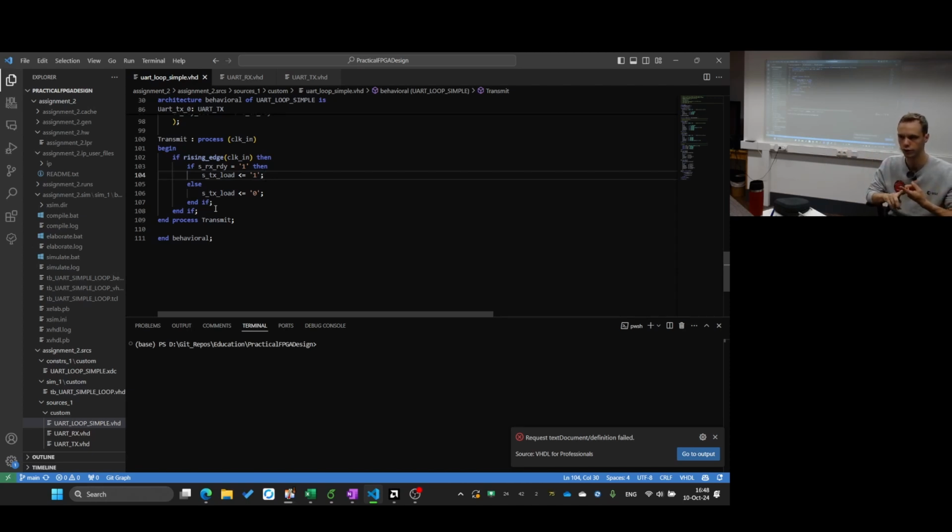We're working mostly with synchronous clocked processes or designs, because this will make the routing easier. This will make your design flow easier, so everything is connected to a clock, almost everything. I will come to the exceptions in a second, but they're technically still connected to a clock. So these are synchronous processes. But can you add prescalers, for example, so that you want a different clock speed, you mean? Yes. We will come to that, but not today. There are various options to do that.